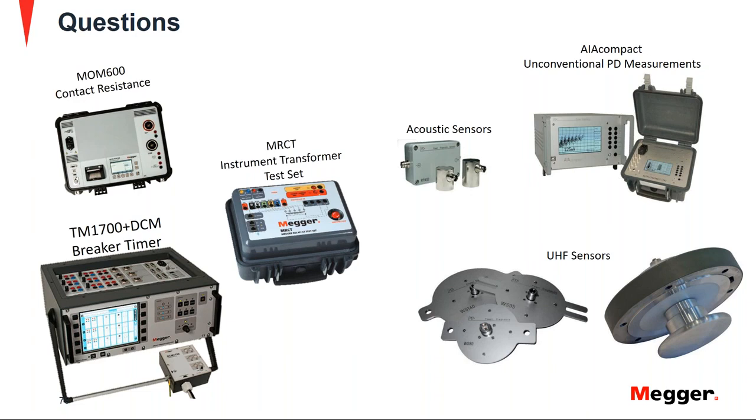There might be other technologies that measure the timing of a breaker, like dynamic resistance measurement, but the resistance changes are too small and too quick that the other technologies cannot detect them. So DCM is a very good way to detect. And actually the slide where Daniel showed the results has at least a bounce in each of the phases. When you get the slides after the presentation, you're going to see that in the slides.